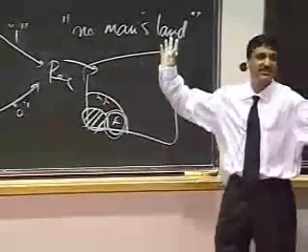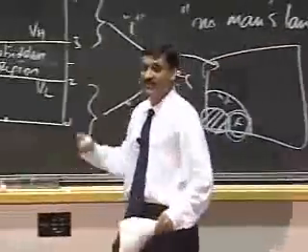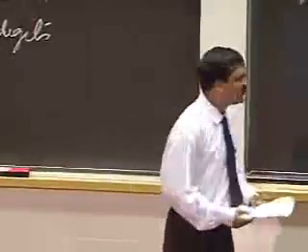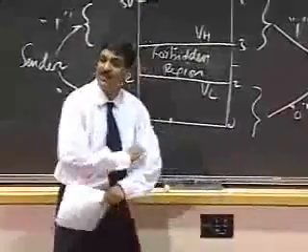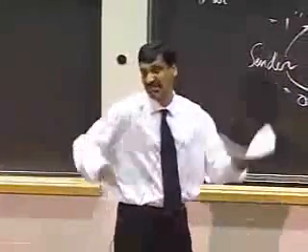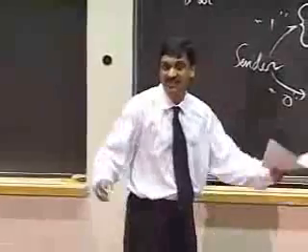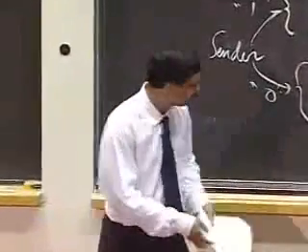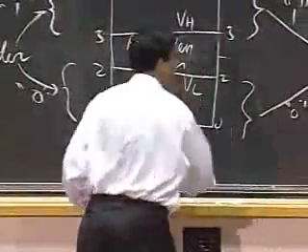So it's up to you. It's undefined. That works. So you, as a receiver designer, can do whatever you want when you see a 2.5. You can say, I'll just put out a 1 if I see a 2.5 or 2.6. No one cares. So this is pretty good.